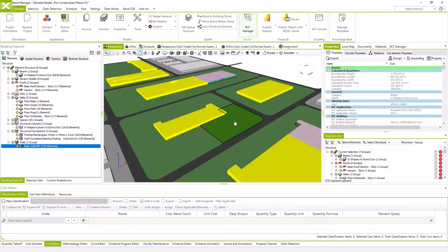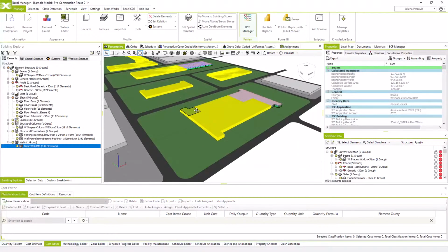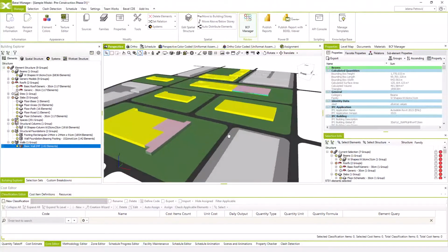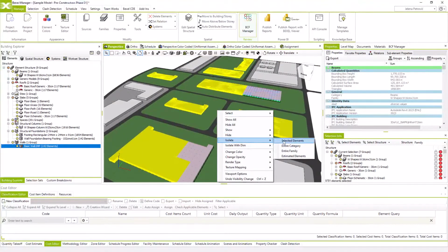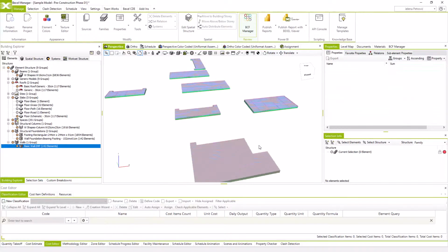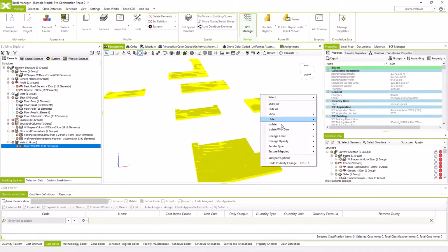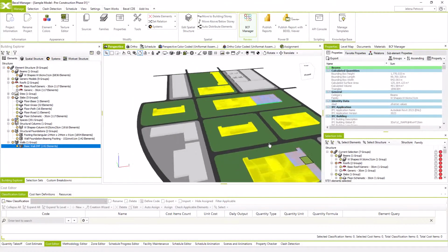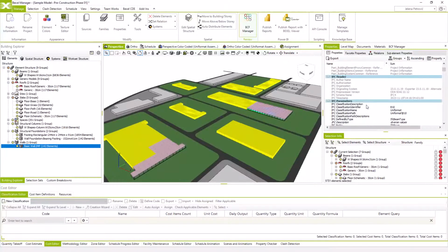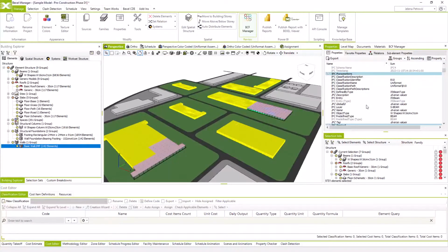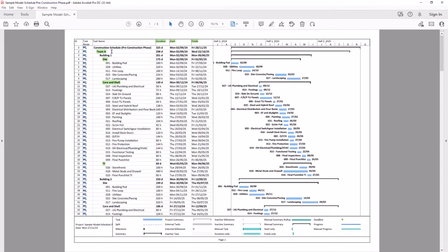This will certainly really speed up process in creating custom breakdowns and smart selection sets creation, but even if we do not have mentioned properties values defined during BIM model development, selection sets could be created manually within Bexel Manager, and also these properties could be set within Bexel Manager by adding related property value for building and zone to certain BIM model elements. So first step is to create selection sets for teams, for Team A and Team B.